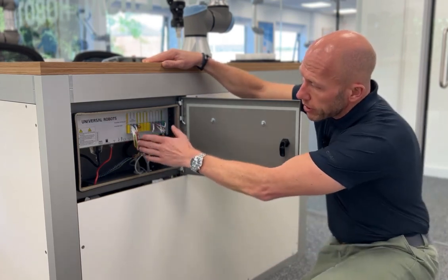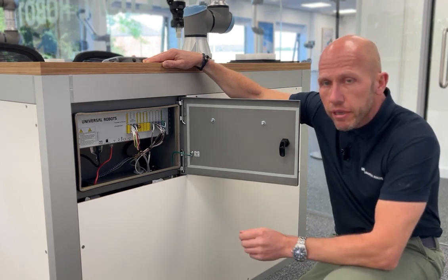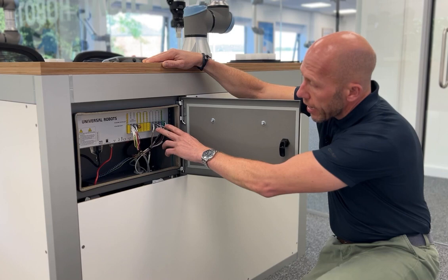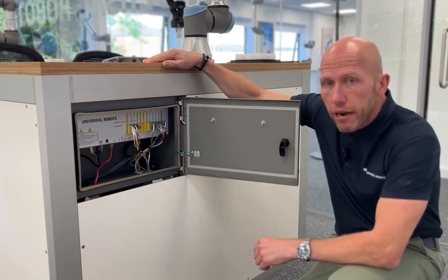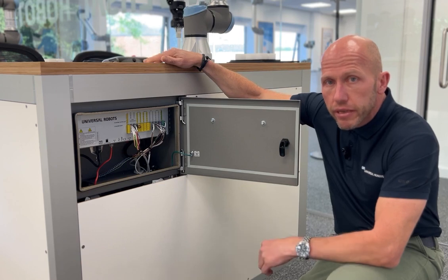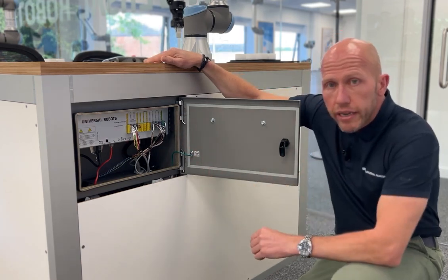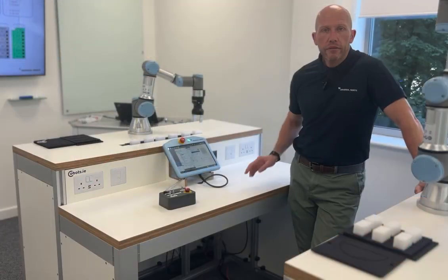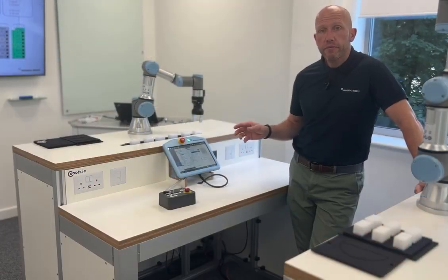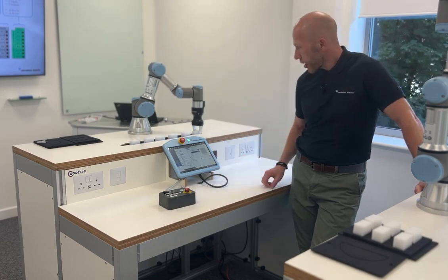We have some additional safety circuits wired in for additional e-stops or safeguard stops, so we can mimic that. Then we have our I/O wired into our inputs and outputs for controlling the conveyor and receiving the signals from the photocells. And then we have our analog signals wired in for our potentiometer. Okay, so now we've interfaced those signals and we've renamed them, we can play the program and see how that interacts.